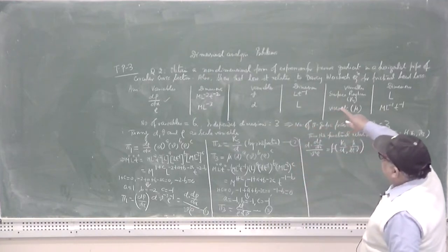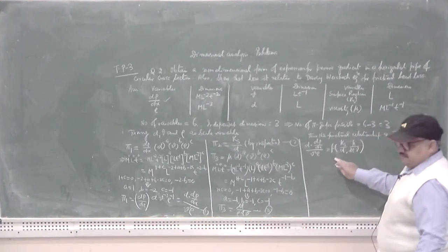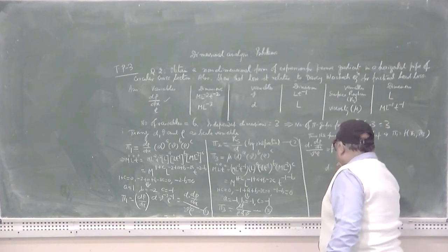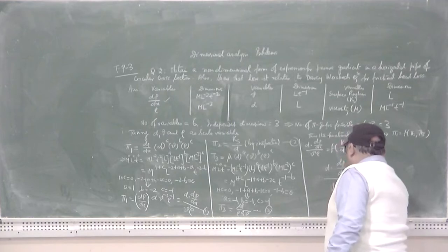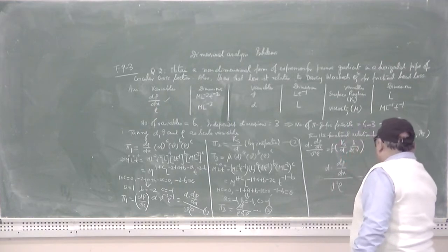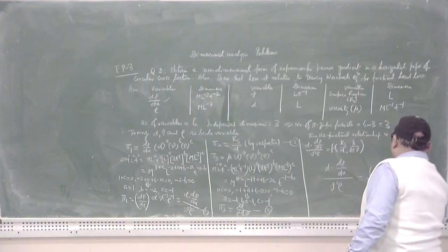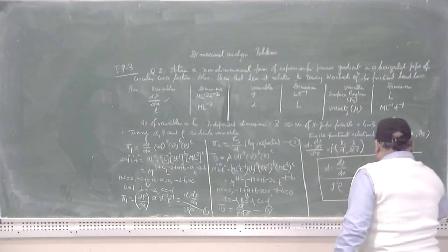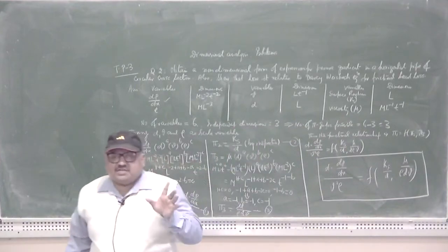Now come to the second part of the question. This is the dimension analysis obtained. So, your first part has the answer: dp by dx divided by v square rho should be equal to a function of ks by d and mu divided by rho dv. Arrival of this result will complete your first part of the answer.